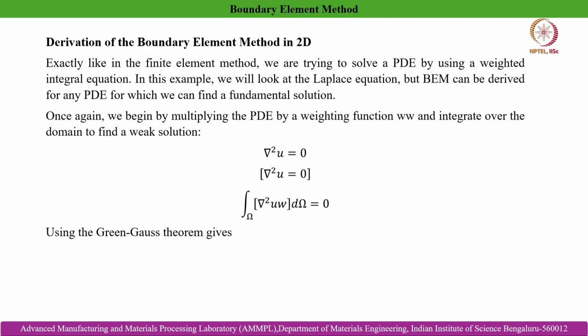So exactly like in the finite element method that we discussed earlier, we are trying to solve a PDE by using a weighted integral equation. In this example we will look at the Laplace equation, but BEM can be derived for any PDE for which we can find a fundamental solution. This is the most important thing: we have to get a fundamental solution to the PDE to apply BEM to solve it.